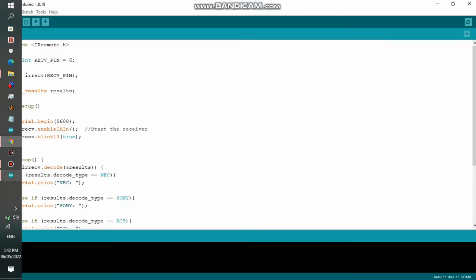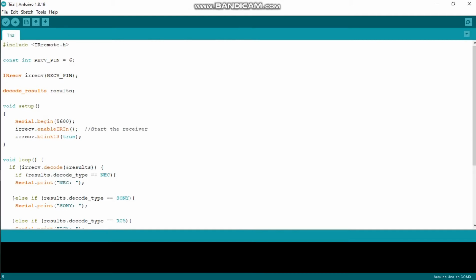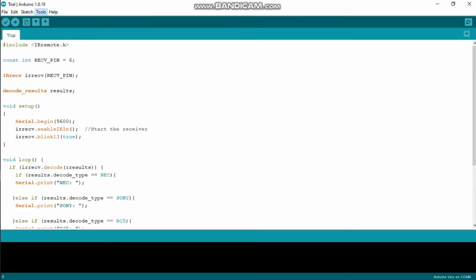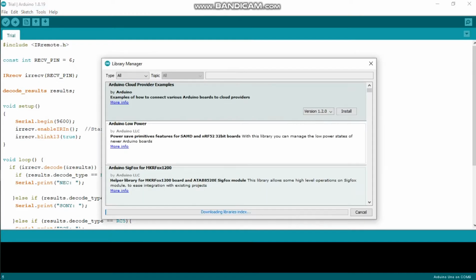I think you don't have a problem with that. Now let's go to our Arduino IDE. I will now teach you how to download the library. So please go to Menu, go to Tools, Manage Library. So wait for a while. Alright, it is here now. So just wait for this to finish downloading. Alright, now please search for IR remote.